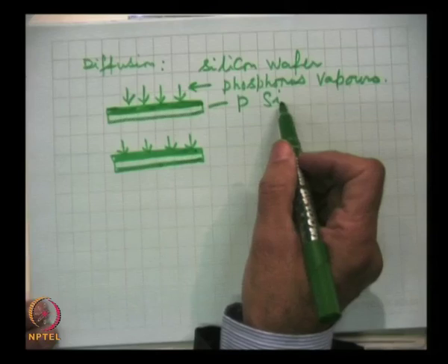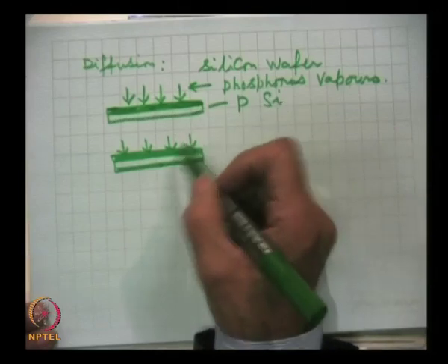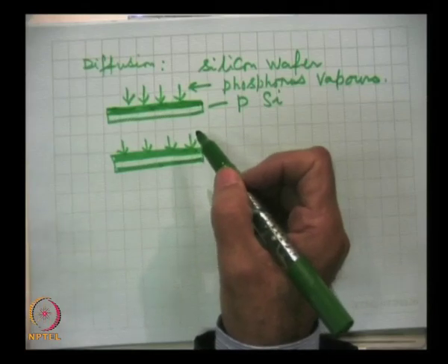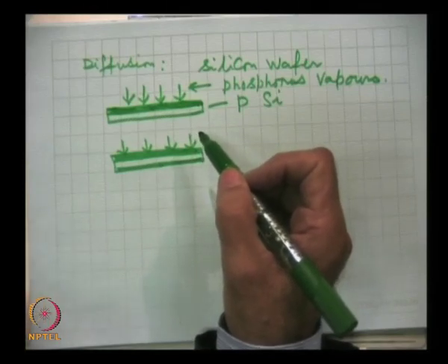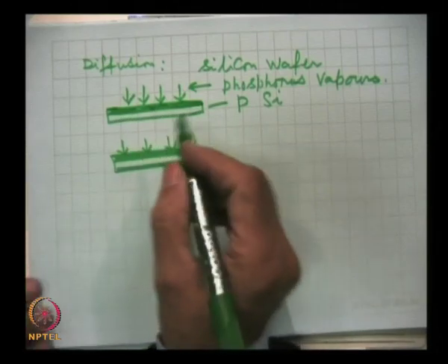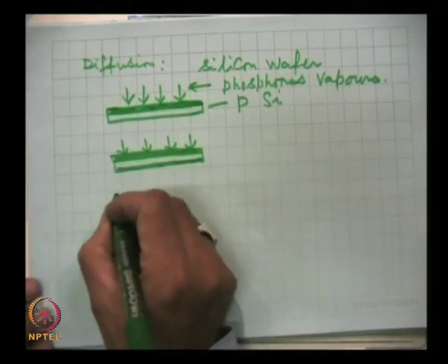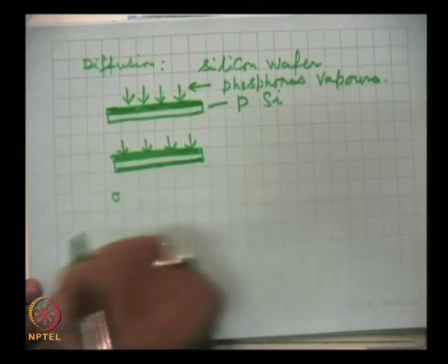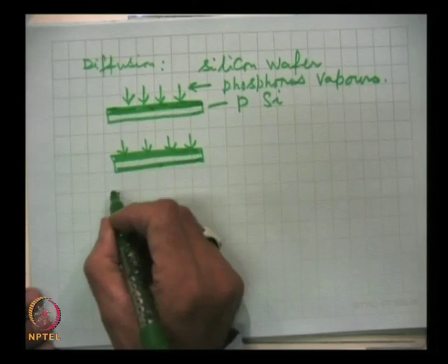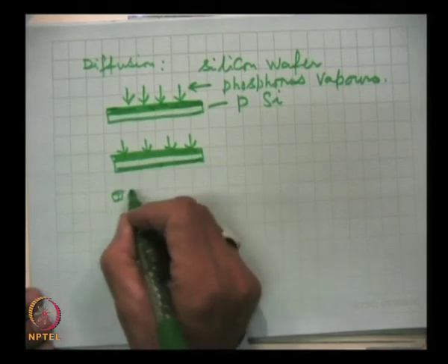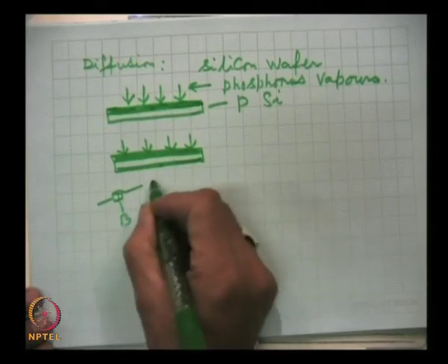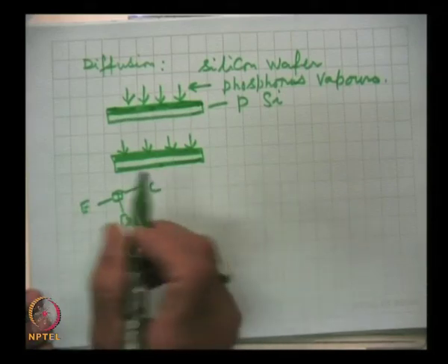We started with a p type semiconductor. Both sides now have n type, but they differ in their doping levels, and ultrasonically we can cut, and each one will be a small chip like this, on which electrical contacts can be made, and then this can be a transistor. This will be base, collector and emitter.